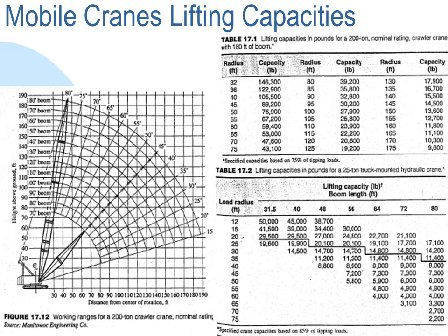If you could see, there is a difference here differentiated by a line between an upper set of values and a lower set of values. The lower set of values are for large radii. So here you could understand that the mode of failure of such a case is actually due to overturning moment. However, for the smaller numbers, the mode of failure is mainly due to structural failure within the cables themselves.